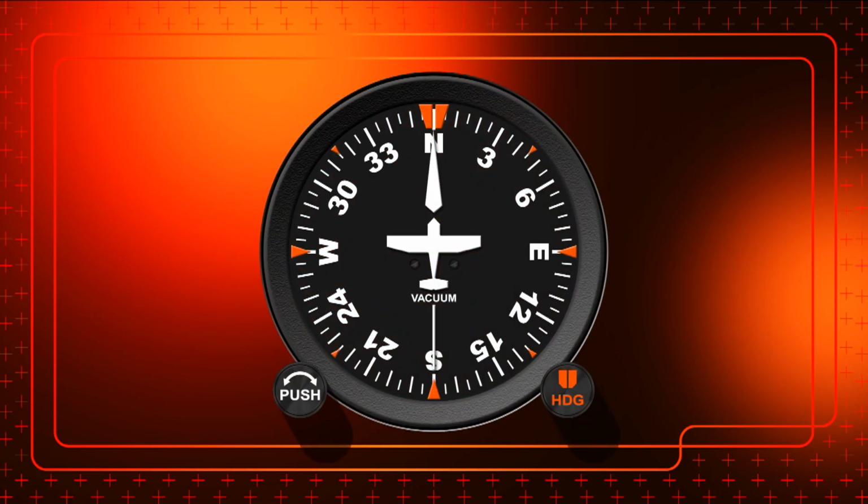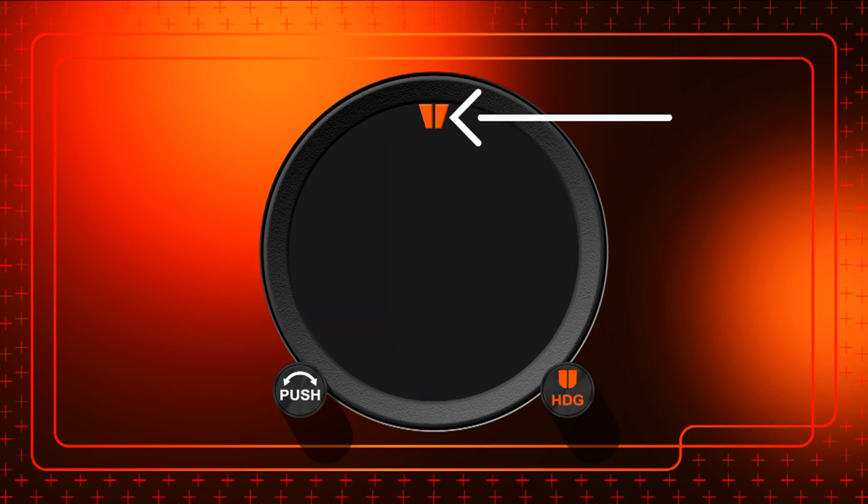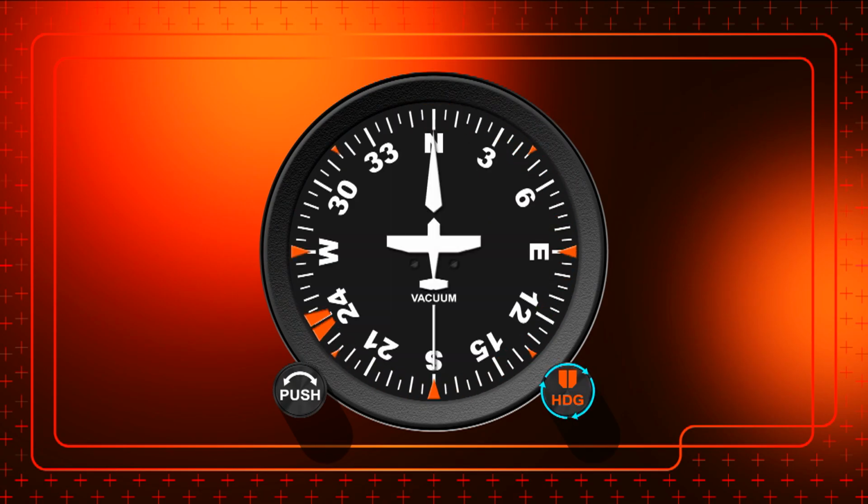Moving on, the indicator also has a heading bug. This bug can be rotated by the pilot so that he or she has a visual reference to what angle they need to turn to when instructed by air traffic control. For example, if you are flying at a heading of 360 degrees and air traffic control instructs you to turn to a heading of 055, you can simply turn the heading knob on the instrument that turns the heading bug,